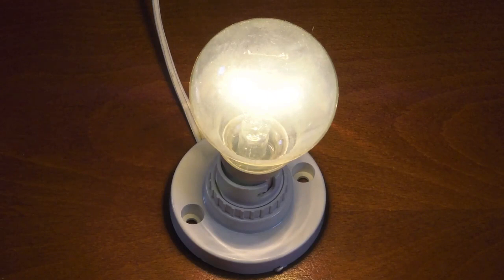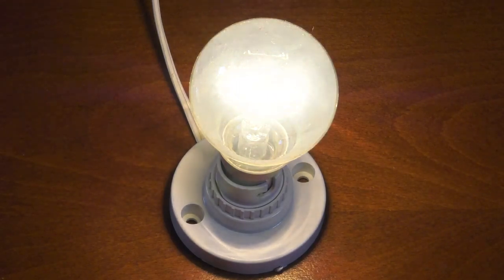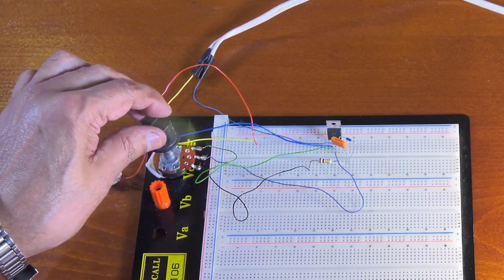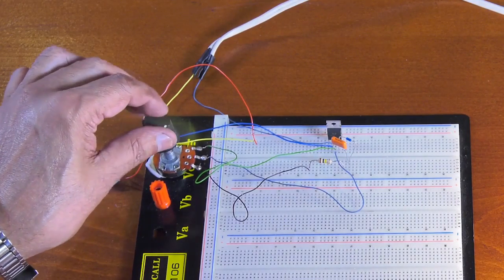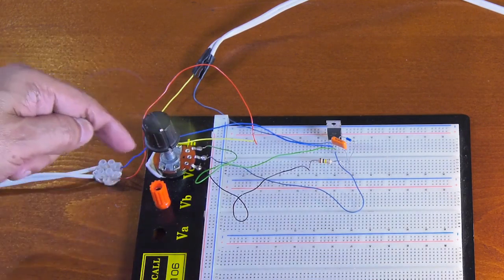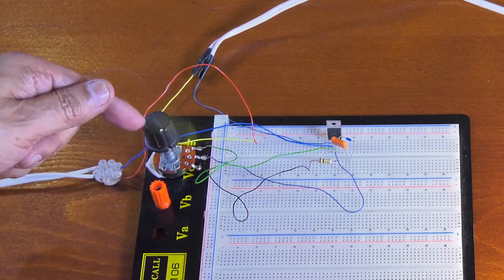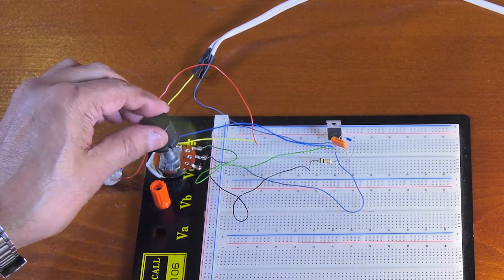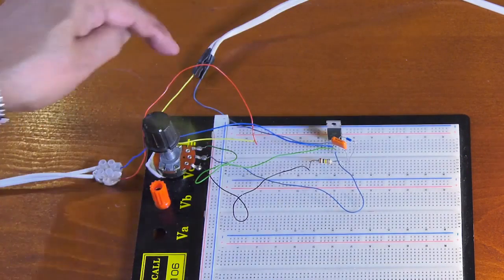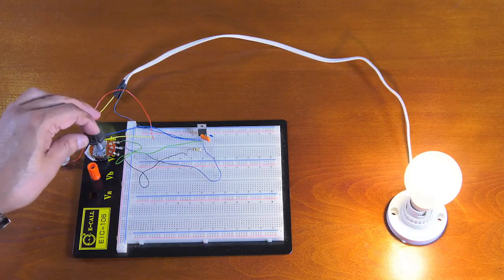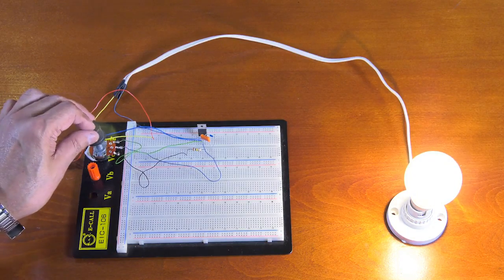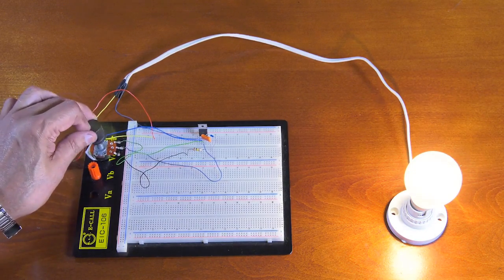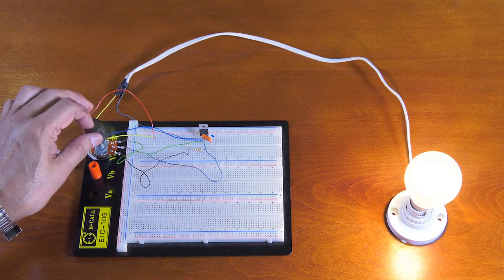Please be very, very careful when you are working with the circuit because it's connected directly to mains. All the components have a mains potential to them, and therefore you should always make sure you have a plastic knob like this one here. Do not touch any metal parts because it could be dangerous. It's connected, as you can see, directly to your mains. There is no battery or anything here. There's no isolation transformer or anything of that sort. So care must be exercised when you are working with a circuit of this nature.